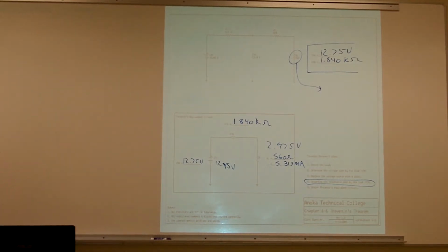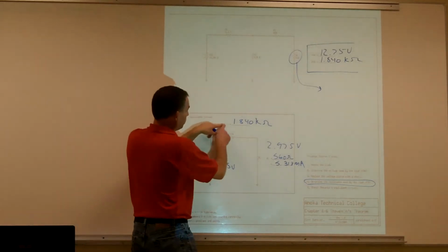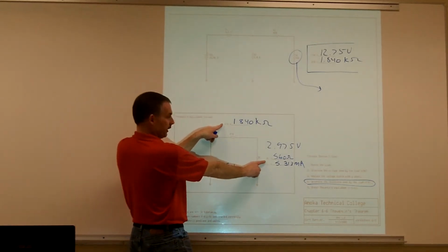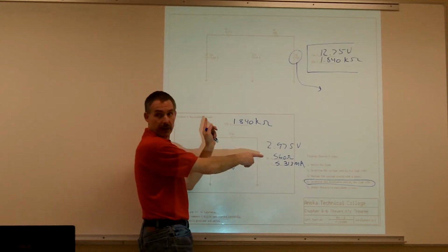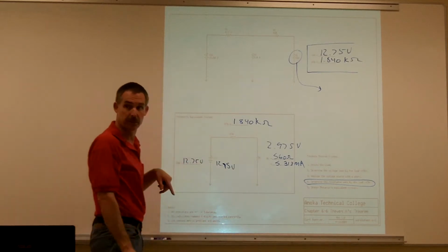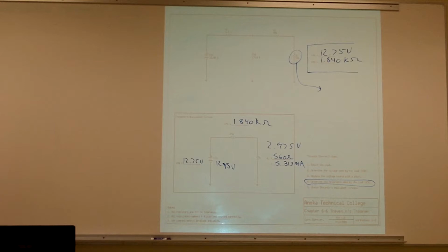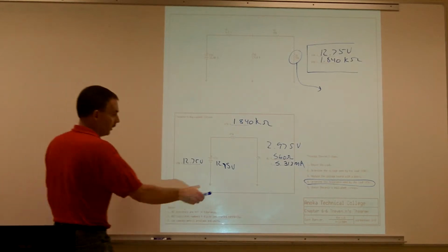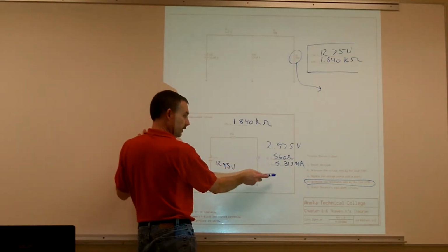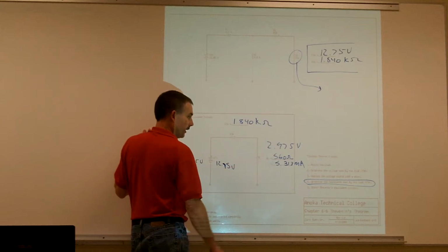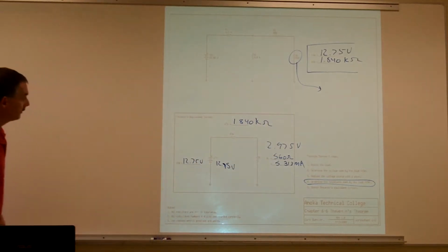How do you get the voltage for the R load right over again? Well, because we know this resistance and we knew this resistance, right? So maybe we can just use our voltage divider formula, and it's going to drop proportionally across the two. Okay. Yep, and then just use your voltage divider formula, calculate out what that voltage is across that resistor, and then you can just take that voltage divided by your resistance and get your current.